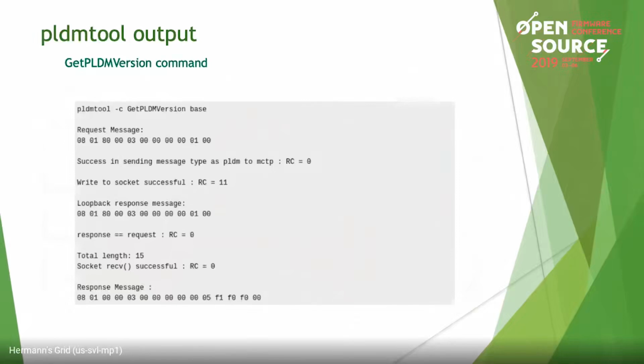Since this is an MCTP daemon, a demux, what was sent by the PLDM tool is looped back again to the PLDM tool, which gracefully discards it. But what comes as a response from the actual responder is processed, and right now it's just printed as bits and bytes. We'll be getting to some of these enhancements later. But we get the MCTP header, we get the PLDM response and the data.